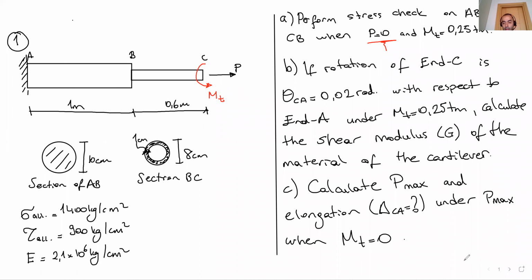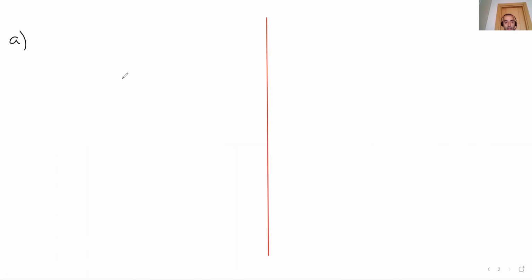So it's gonna be like here. This is the cantilever, you know. We convert the MT to a vector like this. This is the MT. After we convert the torsional moment to a vector, we can assume this as an axial force, and then we can draw the axial force diagram that gives us the torsional moment diagram.